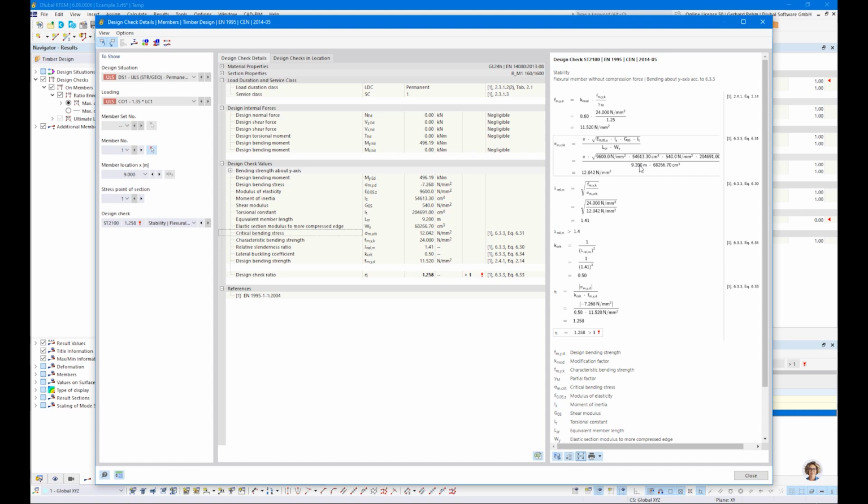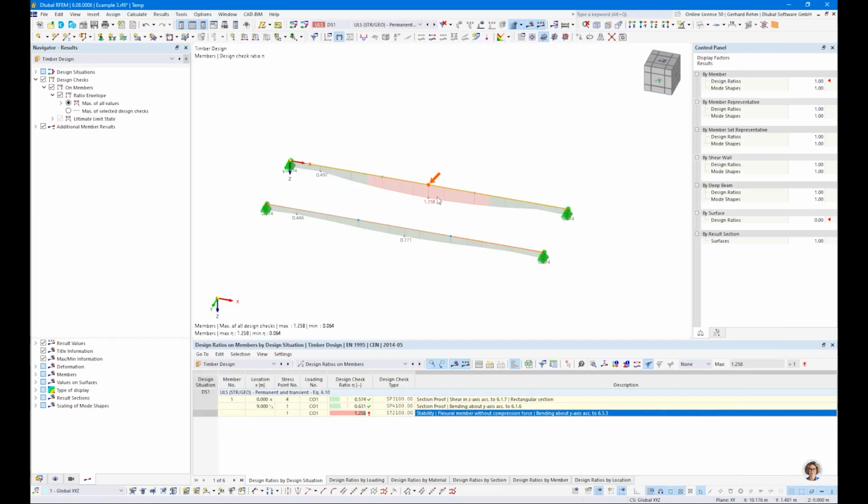It's nothing else than 18 divided by, we have 3 spans in this case, 6 plus 2 times 1.6 meters equals 9.2 meters. So maybe this approach is not correct. The buckling length in reality is smaller. But we do not focus on this method. We focus on the eigenvalue solver method because it gives us better results.